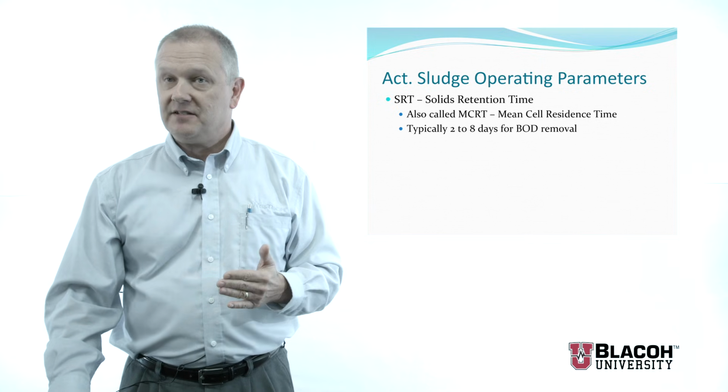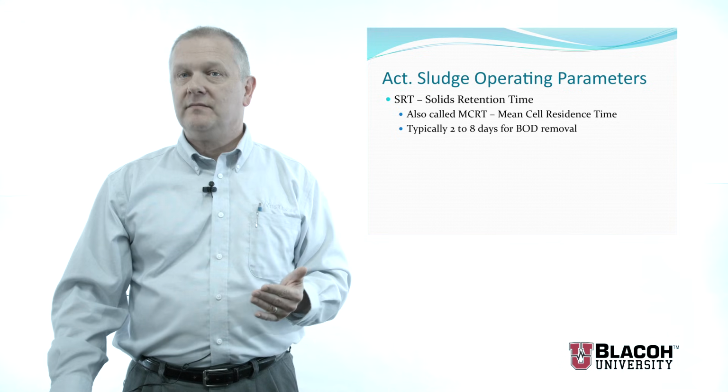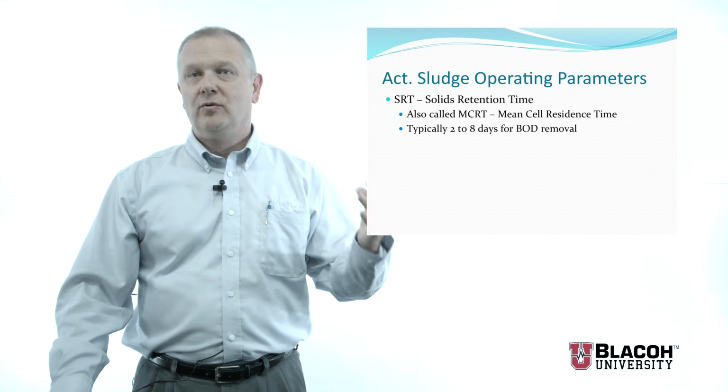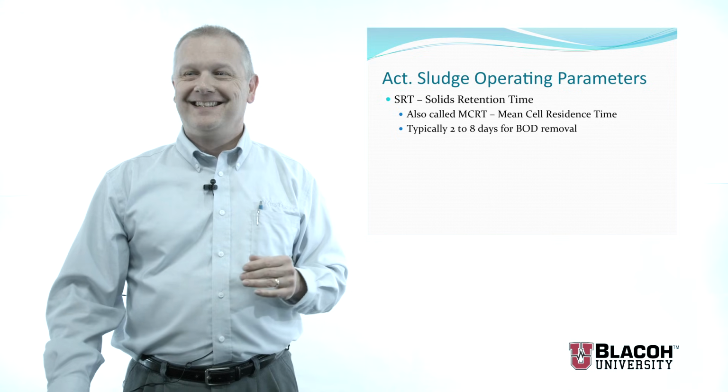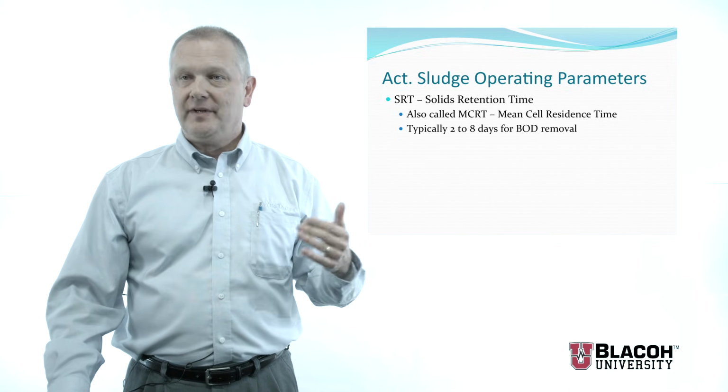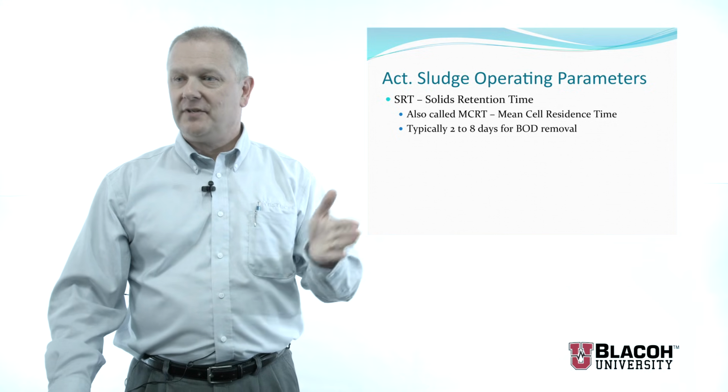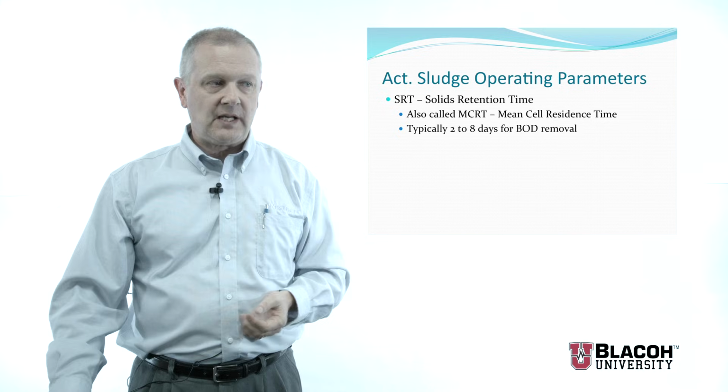Typically, it's 2 to 8 days for simple BOD removal. If we get into nutrient removal processes, which is another class that we'll talk about, it's even longer. But for typical BOD removal, most wastewater plants, this solids retention time is between 2 and 8 days. It needs to be long enough that we allow the organisms to reproduce and grow. If our SRT is shorter than the reproductive cycle of the microorganisms, they'll be out of the system before they reproduce, and we can't get the concentration we need to do the job. So this is a very important parameter that we have to design for.